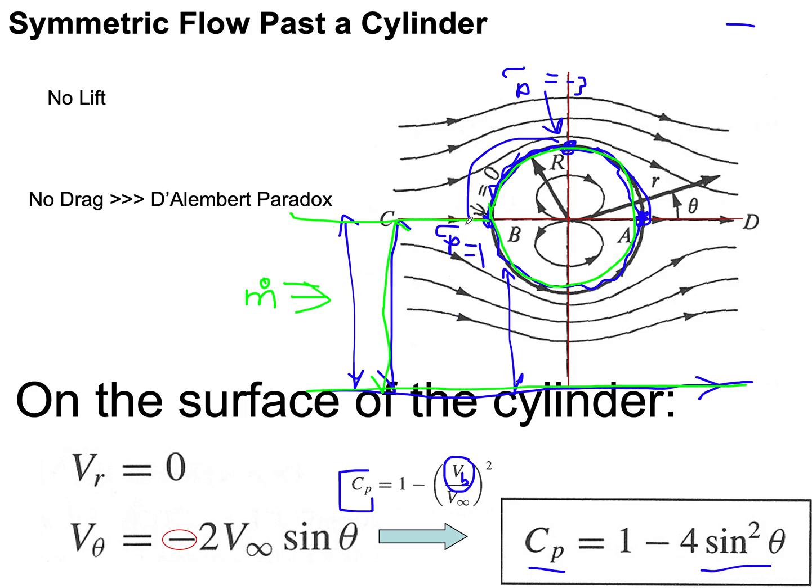And you'll see as I get closer to the body, here's a stagnation point. As I look at the distance over here, my mass flow rate is going through a smaller area, so it has to speed up, and I get the minimum area right here, so I get the maximum velocity. But then as I move further downstream, the area starts opening up again until I get to my stagnation point again, and then my flow tends to become more and more uniform further away.